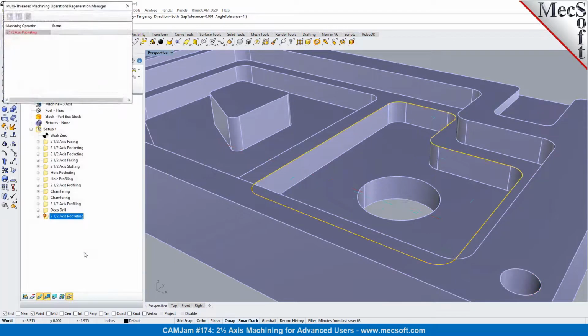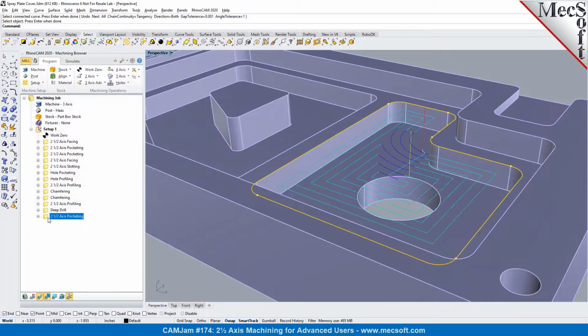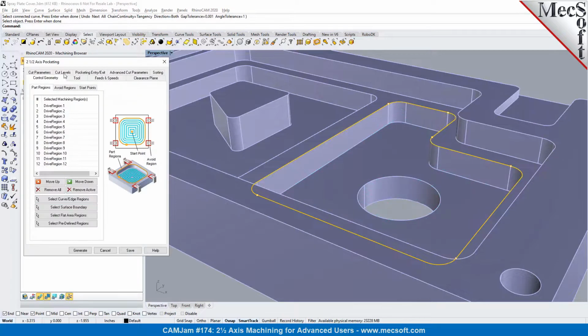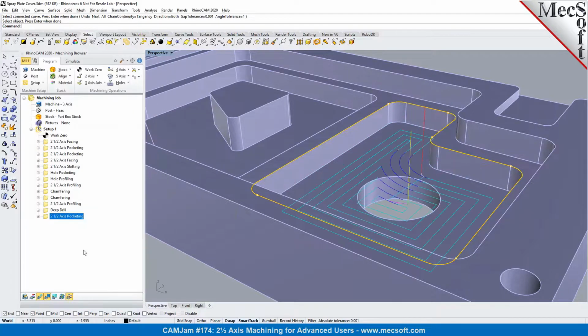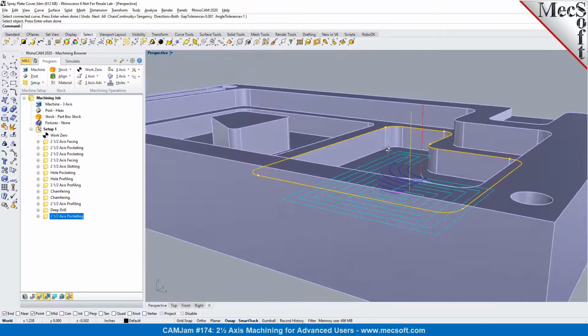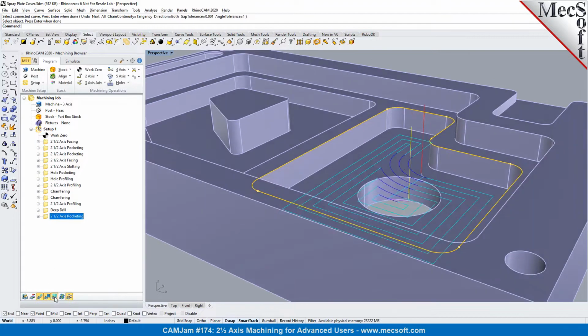So when you generate the toolpath, you will notice that the depth will be determined, and you can just specify a depth per cut. If I put in a depth value that's larger than the depth, it'll just insert one cut level at the floor where the depth is automatically determined, and you can see the Z level right there.